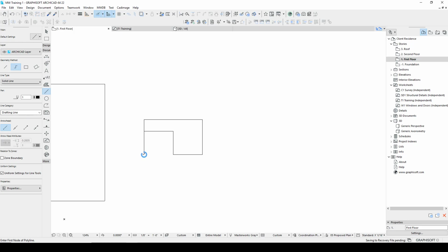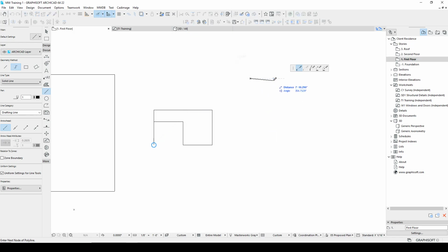You're going to want to choose how you do that most of the time, or find a combination that works for you, which is probably kind of what I've done. So when I'm drawing these lines, I can, again, I'm starting, and if I hit Tab and I keep hitting Tab, you're going to notice that there's some more options here. And when I first started using ArchiCAD, I used X and Y a little bit more than I do now. So I can hit X, say 6 feet, Y -2 feet, and then I'm drawing a line that's 6 over, 2 down.